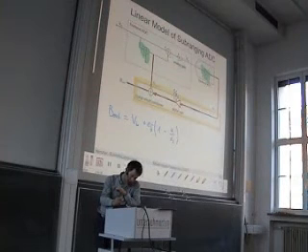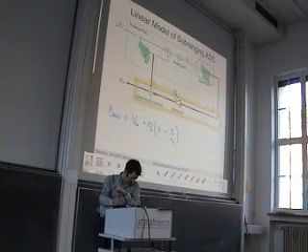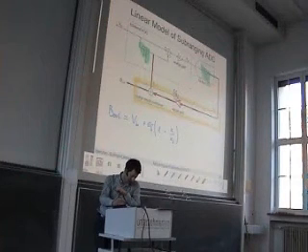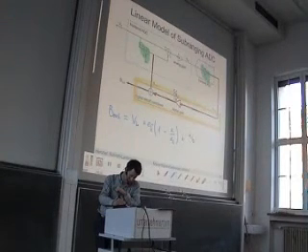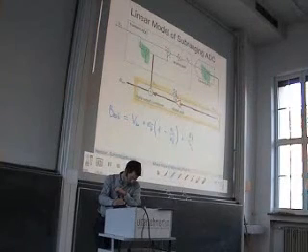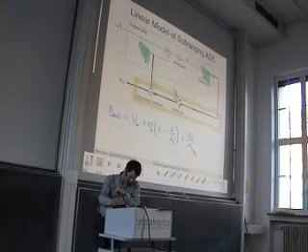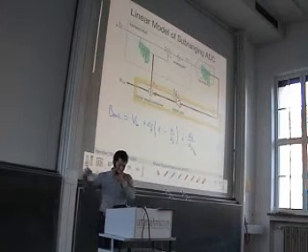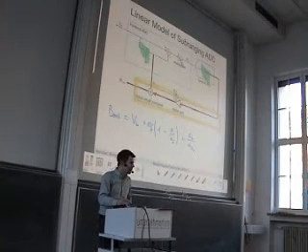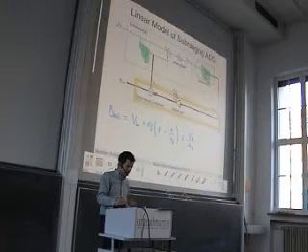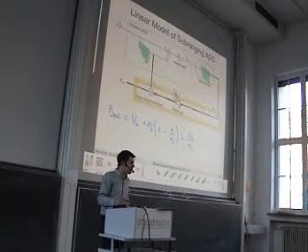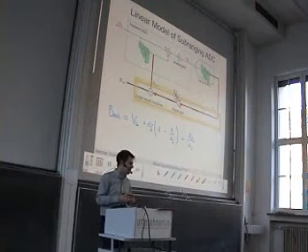And finally, we have this quantization error of the backend ADC. Multiply this by 1 over AD and have it visible at the output. So we have plus E backend over A digital. This one is called A, the analog gain, and I called this AD, which is equal to this one, A digital, because this is one in the digital domain.